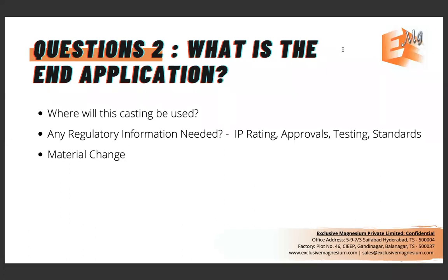If you have mobility as one of the requirements, it's always better to go with magnesium for a heavy component, because that would significantly improve your runtime, and that's something they can consider whether it's a priority for the customer or not. That's one place where we can come in and tell you that maybe there's a better alloy you could use for your end use case.